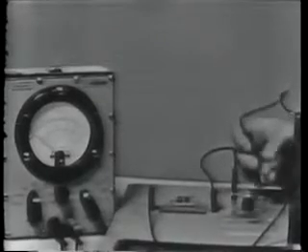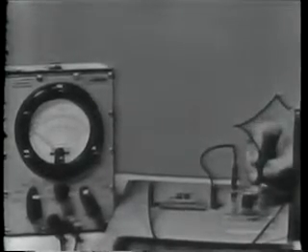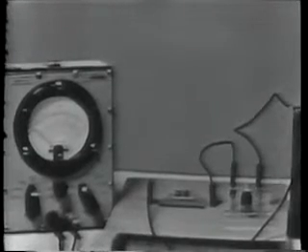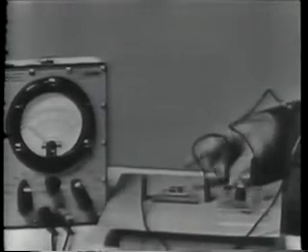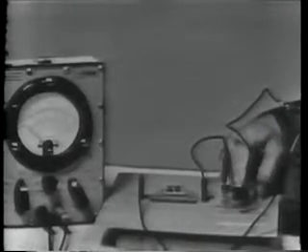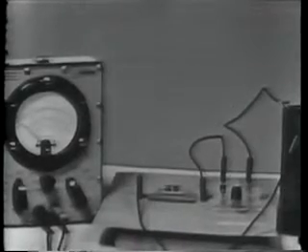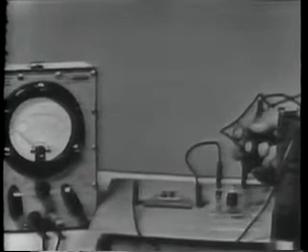When I connect the unconnected terminal of the lamp back to the other side of the batteries, the circuit is complete. Notice now, even though I have all terminals connected, the lamp does not glow. So with the voltmeter, I'll take measurements across the lamp and the resistor. You record the voltmeter indication as I go. Spaces are provided under number 3 on your response sheet.